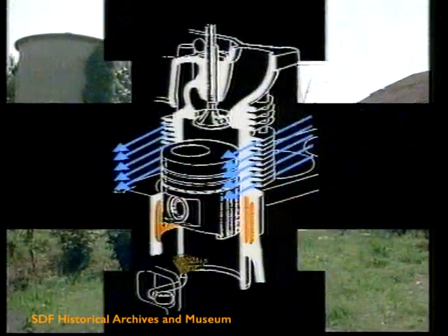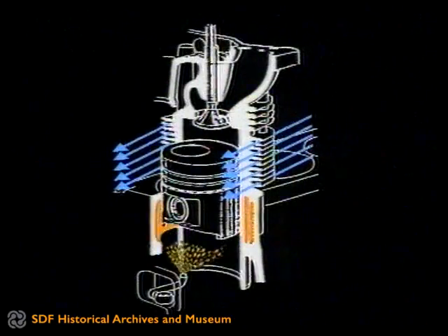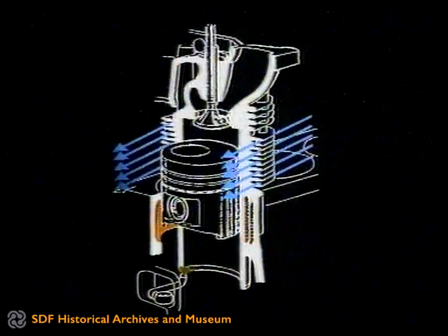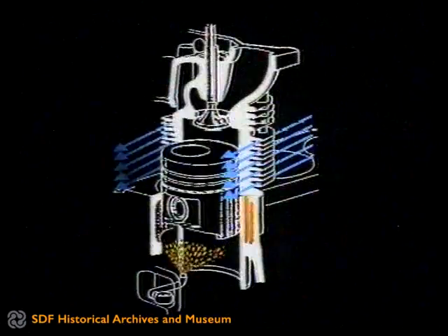Mixed cooling of cylinders. Forced air circulation cools the cylinder heads and upper sections, whilst pressurized oil cools the bottom sections of the cylinders by circulating around them in suitable cavities cast in the cylinder block. Inside, a powerful jet of oil under pressure directly cools the pistons and the cylinder walls. This is the most advanced cooling system in existence today on the diesel engine market.